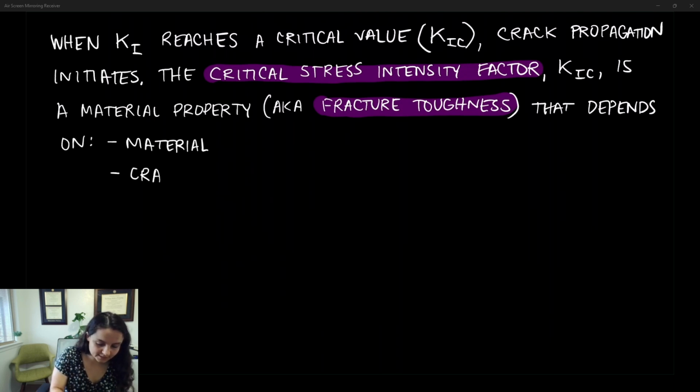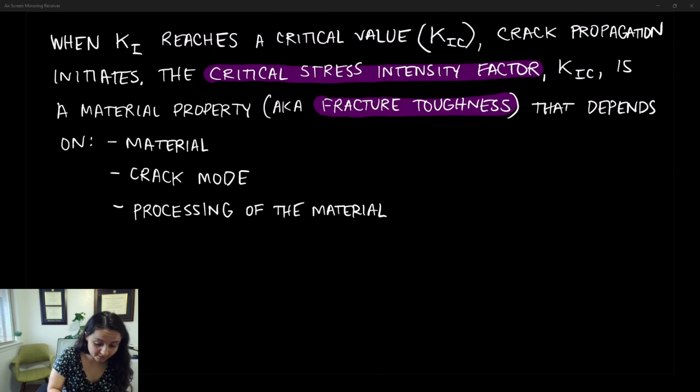It also depends on the crack mode. So K1C is different from K2C, is different from K3C. So depending on which mode, opening, sliding, or tearing, that you're looking at. It also depends on the processing of the material. I already mentioned that. But yes, heat treatment matters. And any other processing that's been done on the material matters. The temperature matters.